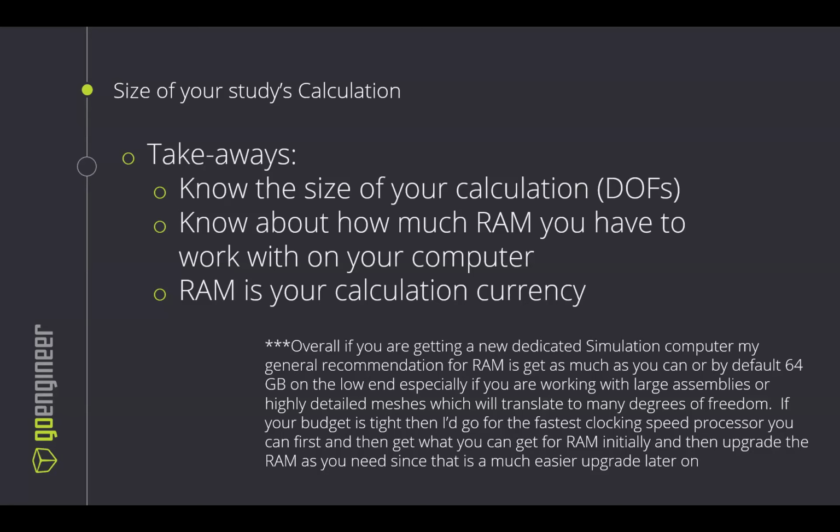You might get an out of core message, or you might get a message like you saw there about the size being too large for the solver you're using. So yeah, know how much RAM you might need for your machine.